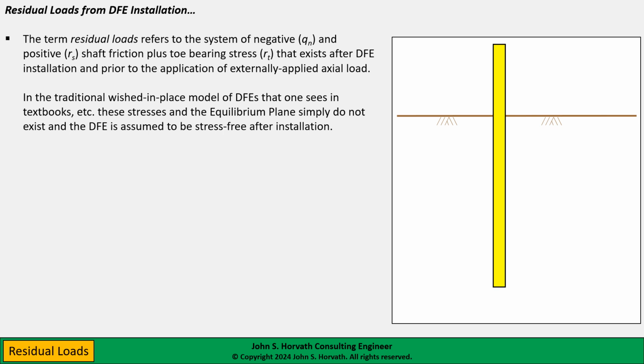Now, in the traditional, what I call wished-in-place model of DFEs that you see in textbooks and other documents, of course, these stresses in the equilibrium frame simply don't exist. And the DFE is assumed to be stress-free after installation.